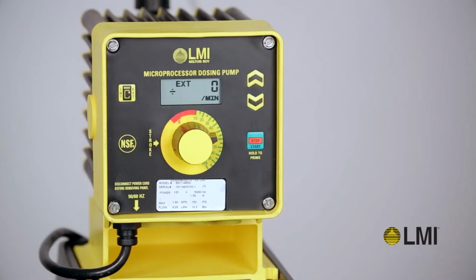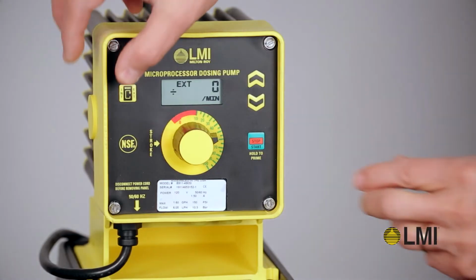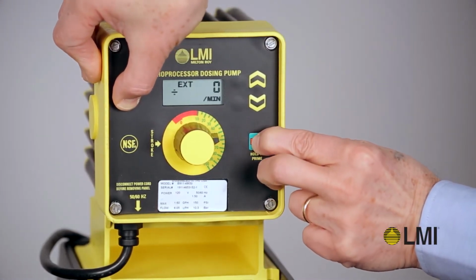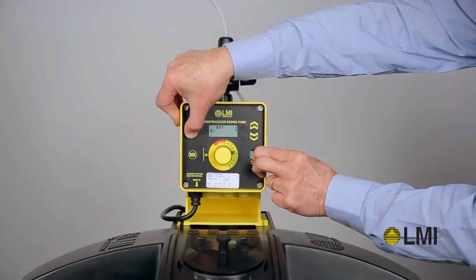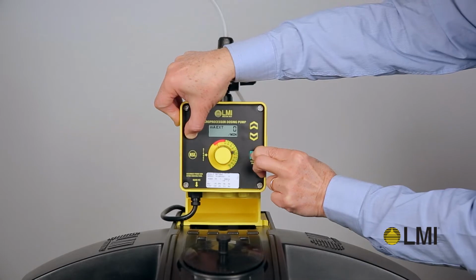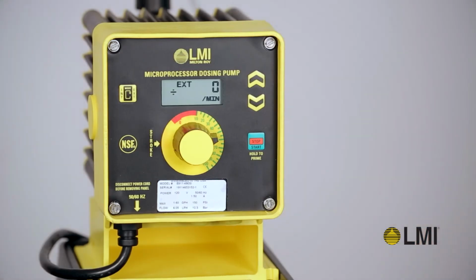The symbol on the LCD will alternate between SPM and off automatically. 0 will display on the screen. To select another programming option, press and hold the mode key and start/stop keys together for 5 seconds. The divide, multiply, or milliamp symbol will rotate on the screen. To select your programming option, release both keys once the desired mode icon is displayed.